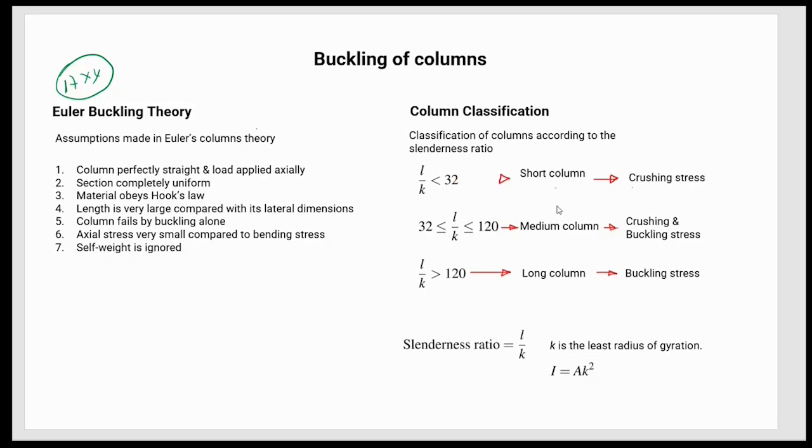Crushing stress is no more than this: imagine this is a column, and then you have a force applied, and this has an area A. The crushing stress, let's put it that way, just to differentiate it from the other, equals what we have seen, the force divided by the area.